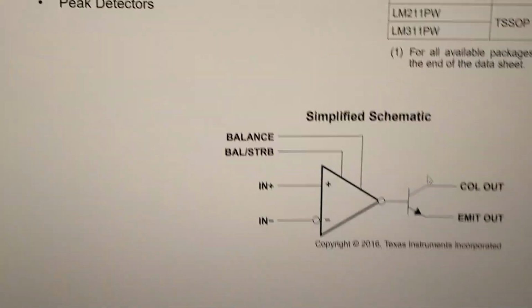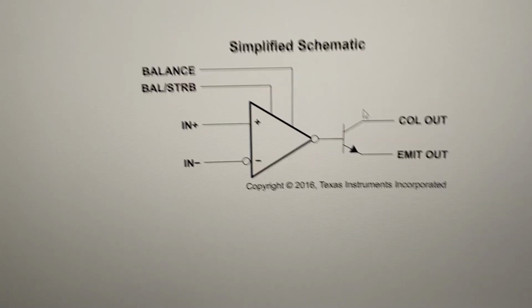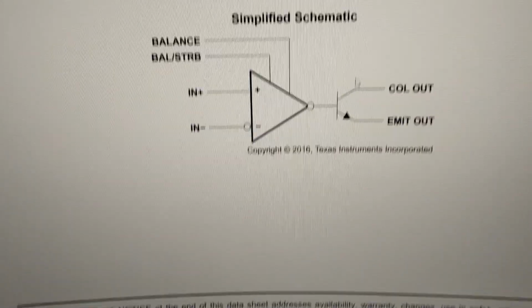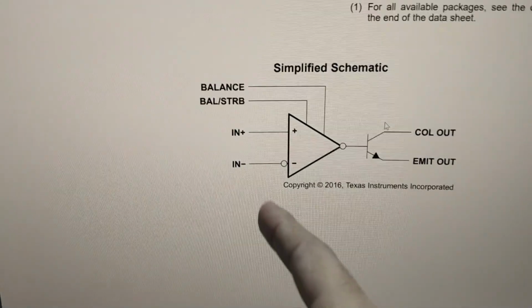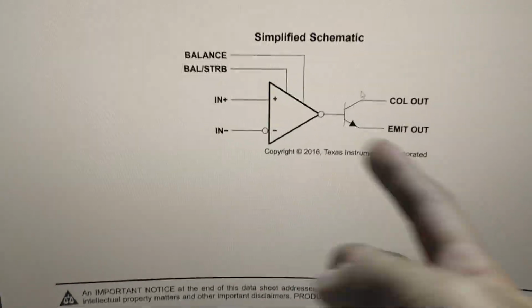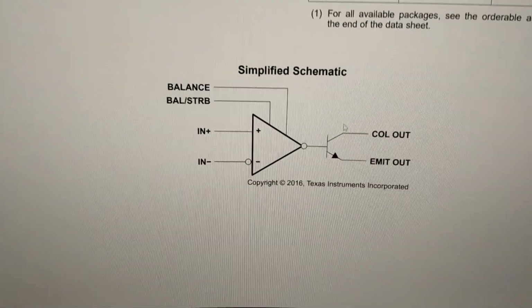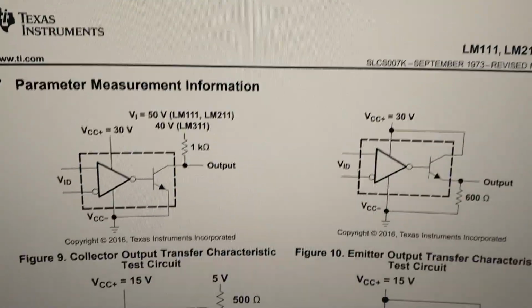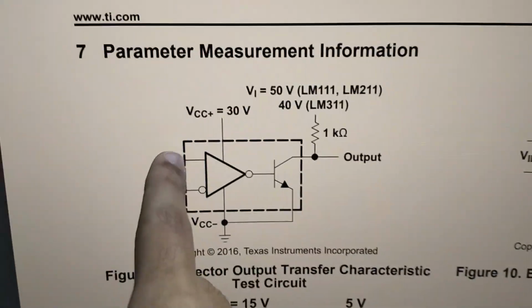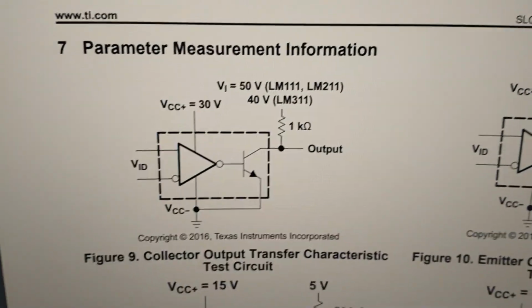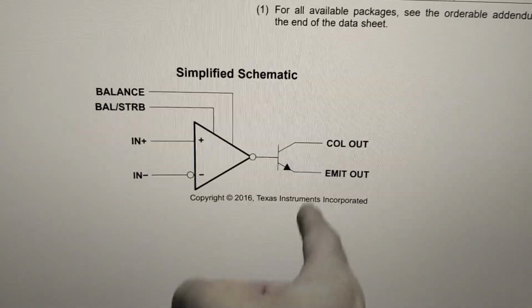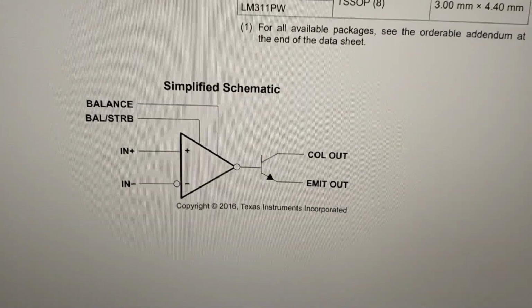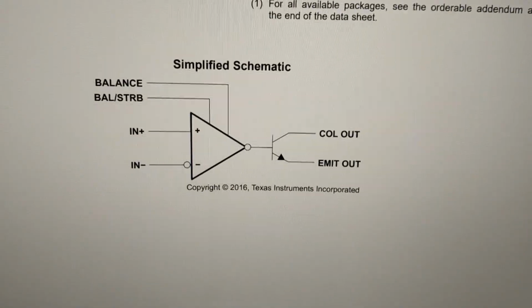And what it does is basically, same as the op amp, the symbol, everything is the same. You have an inverting input and a non-inverting input, and if the inverting input is higher than your non-inverting input, the output, in an op amp, would go high, but if you see here, there's a BJT here, so basically it has an open collector output, and it looks like this. So basically if your inverting input is higher than your non-inverting input, then this BJT is going to turn on and basically pull the output to ground, just like how a normal BJT behaves.